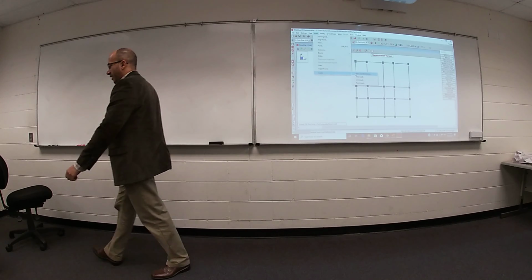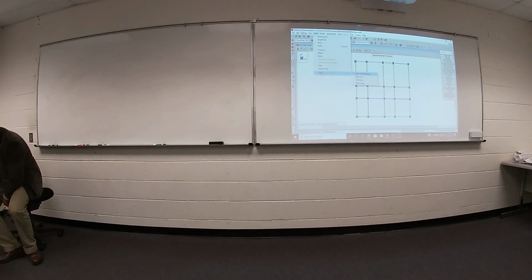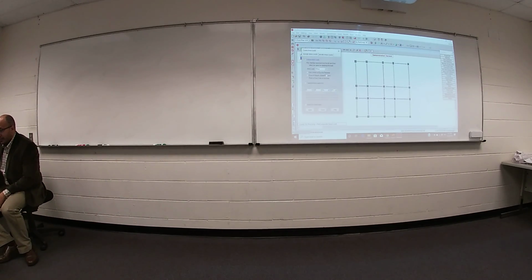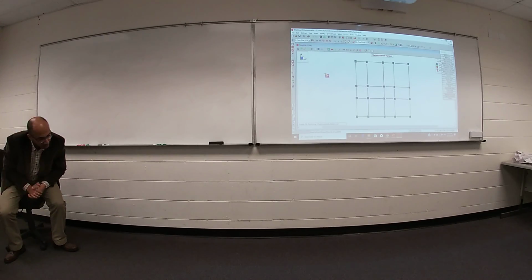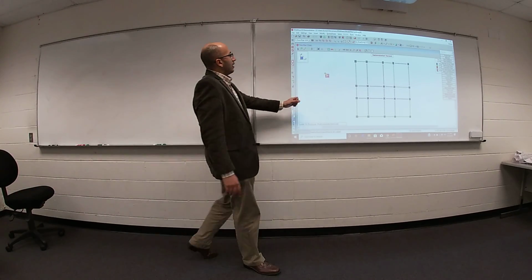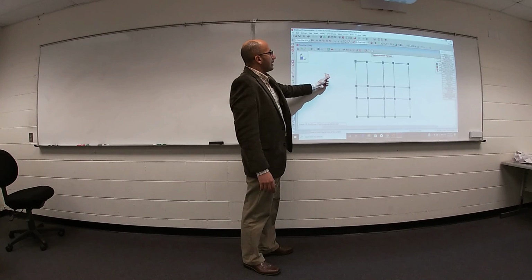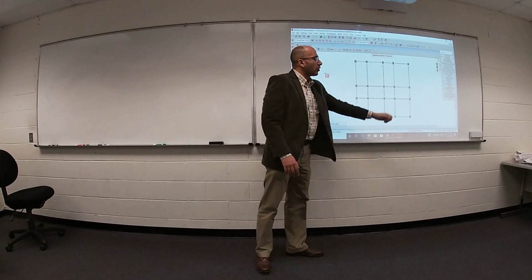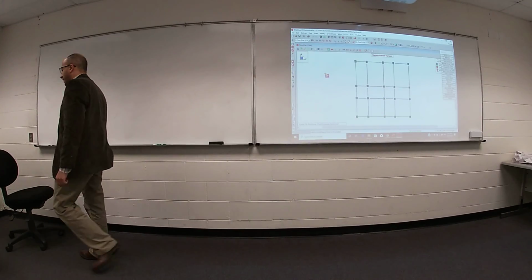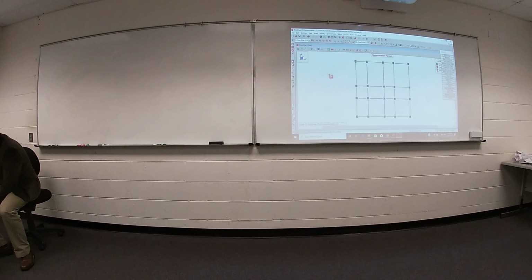Anyway, so area load, my live load will be office, building, apply. I am ready. Your mouse or your arrow is ready to define where is your load. Just click on each area of your slab.